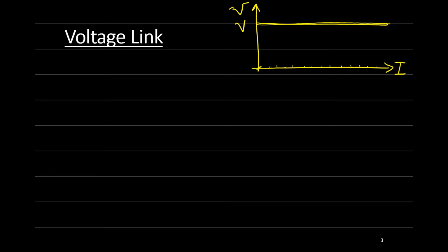If we have voltage source, that means we have a constant voltage, and the load can be operating at any current. So we cannot say, for example, if we have a voltage source, we connect this voltage source to another voltage source. For example, we cannot design a voltage source converter and connect this converter to the grid, because the grid is another voltage source. So voltage source and voltage source don't mix.